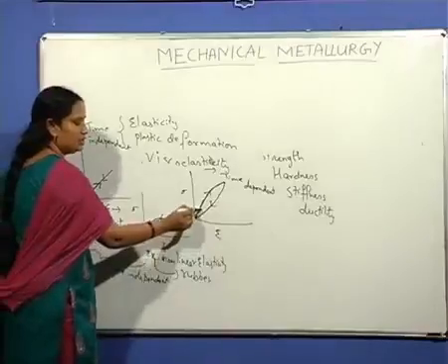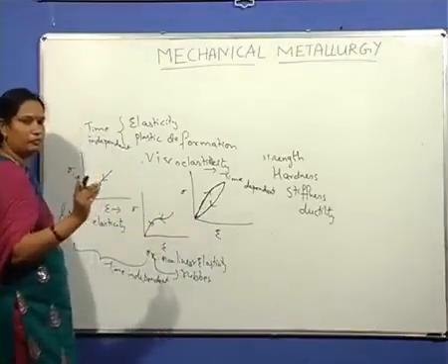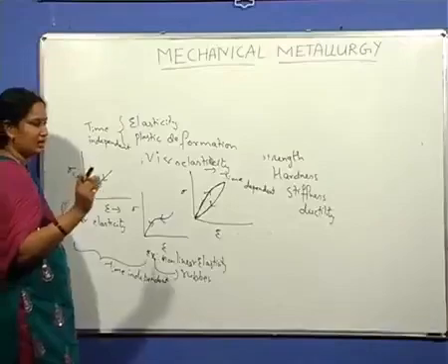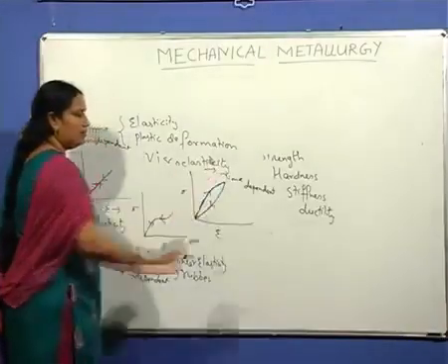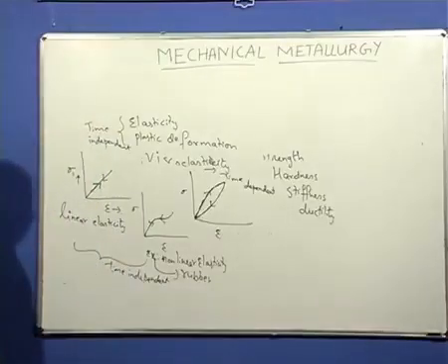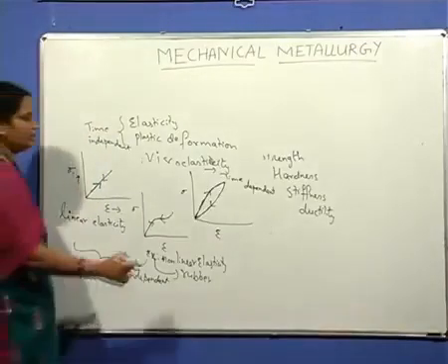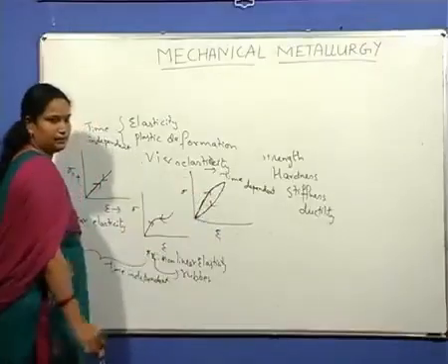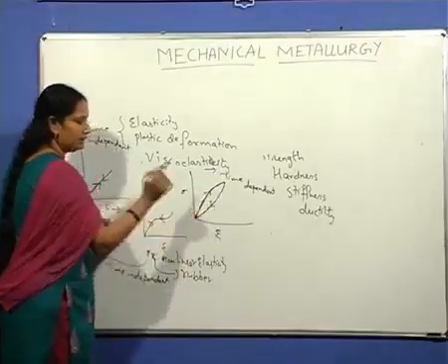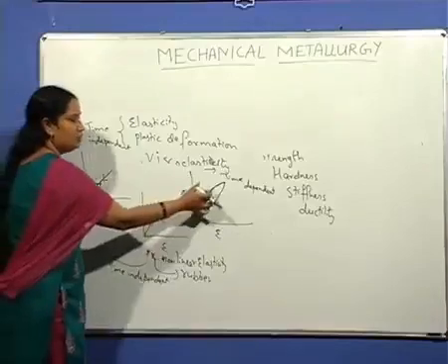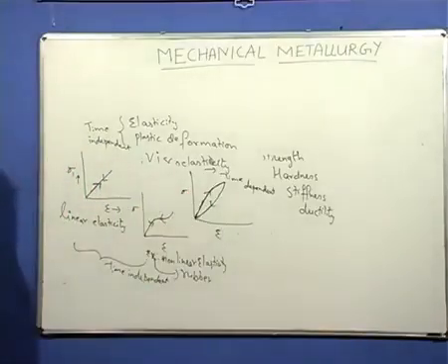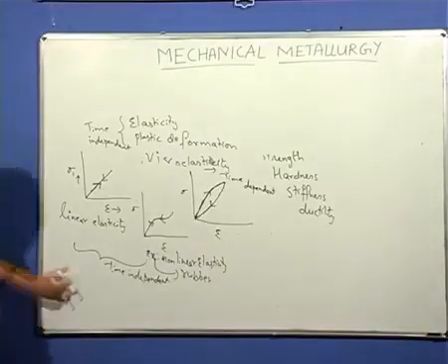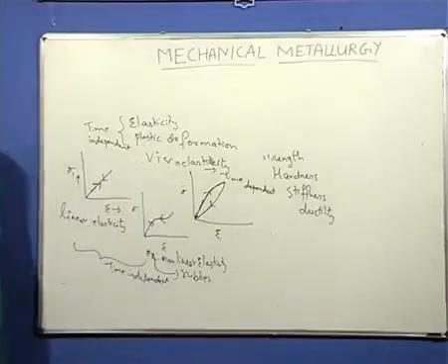Initially, the material undergoes a small amount of linear elastic strain, and then with increase in stress, it undergoes some asymptotic value of strain. Upon unloading, it does not follow the same path. It follows a different path, and this amount of strain is recovered; viscoelastic strain is recovered sluggishly. With respect to time, the strain recovers. So this is known as viscoelasticity.